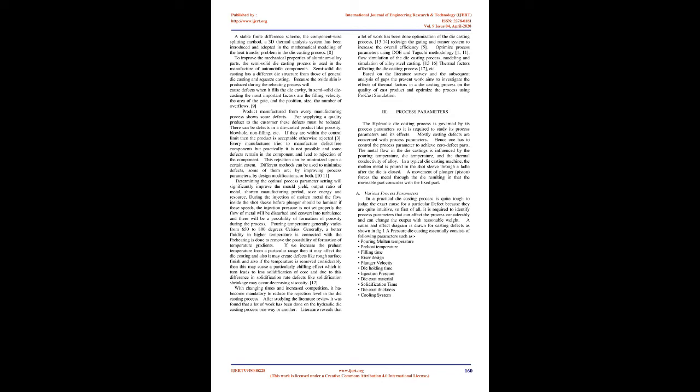Die-cast parts are important components of products ranging from toys to automobiles. Parts can be as simple as a sink faucet or as complex as a connector housing. Die casting is one of the fastest and most cost-effective methods for producing a wide range of components where molten metal is injected into a permanent mold at high speed, 10 to 100 m/sec, and under high pressure. However, to achieve maximum benefits from this process, it is important to maintain the critical parameters of the process.